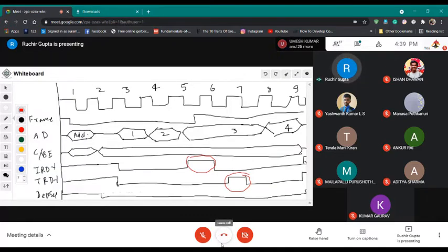Initiator is ready for a couple of data cycles, and then, it's a bar signal, so it is active low, it is getting high for some time, and then again it is getting asserted. Similarly, target ready is getting unready for some time, and it is again getting ready.